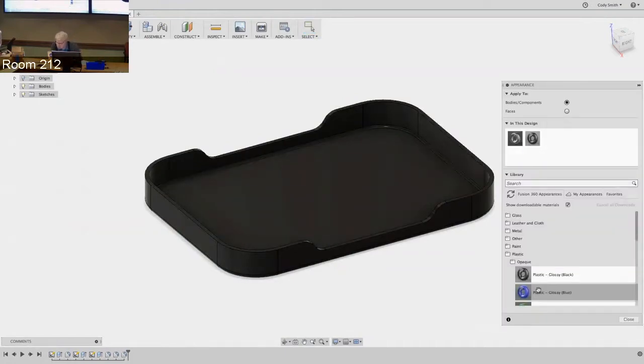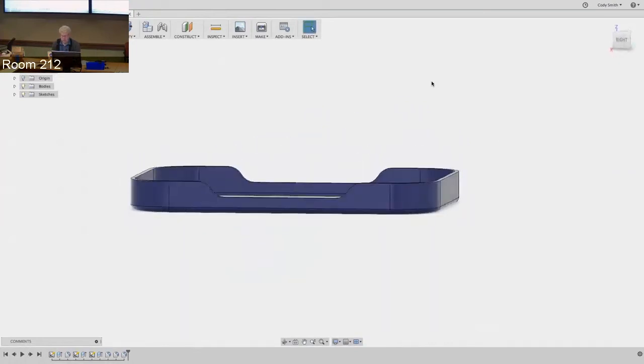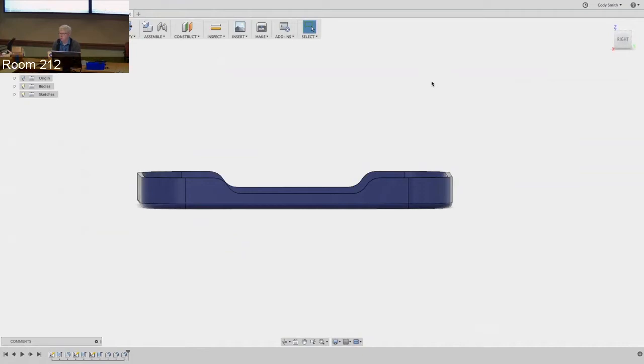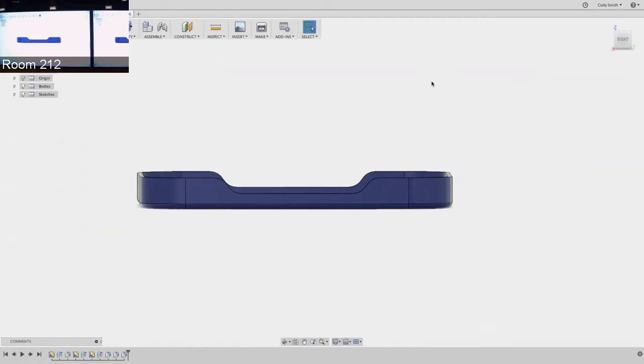Yeah, please. Like for the small fillets, that would actually print itself. Yeah. So the layer size of a print and the width of an extrusion you can tweak, but for this printer, 0.15 millimeter layer height is what you can expect to get reasonably, and with that nozzle you can expect the 0.48. So you can think of like a 0.48 by 0.48 by 0.15 box, and that's kind of at the level the printer's doing.